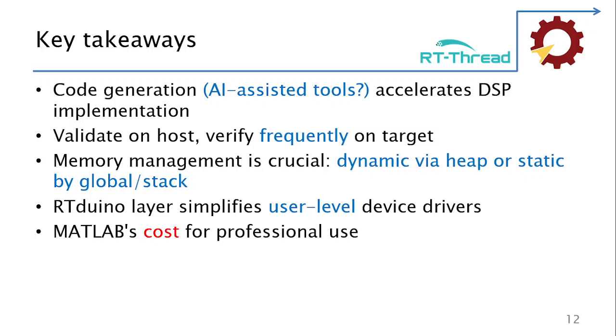It is not just copying the files generated from MATLAB and using them directly. You need to do quite a lot of optimization to ensure that the memory used inside the hardware is not in a critical state. For me, because my code used just 100 data points, 8 kilobytes is okay, but 8 kilobytes of RAM may not be suitable for many applications.